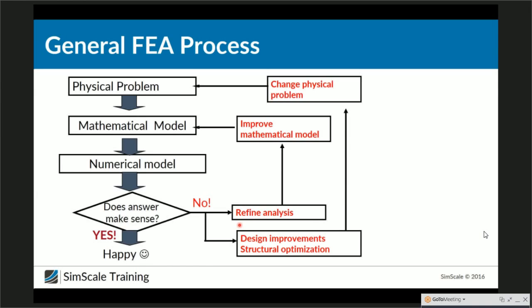Just imagine, right now we are only calculating displacement and stress for the points of the nodes. And using shape functions means that we get this kind of discrete result. So for every node, we have a result which is constant until we reach the boundary of the next node. And this is very important to understand, because in the end, the quality of your simulation mainly depends also on how you modeled it. And in the end, you need to know where the limitations of FEA are. And one of them is very much related to the fact that we're using shape functions here.